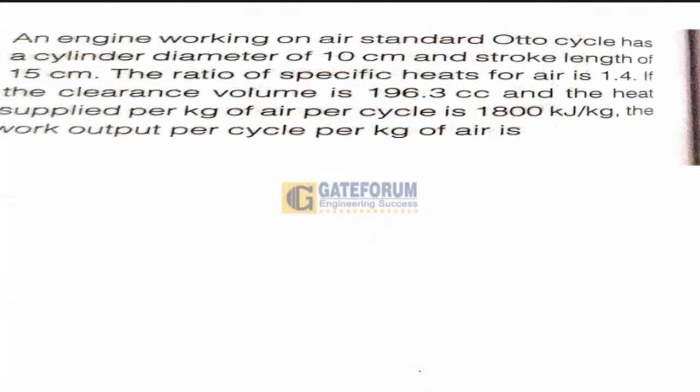Take this question. An engine working on air standard Otto cycle has a cylinder diameter of 10 cm and a stroke length of 15 centimeter. The ratio of specific heats for air is 1.4. If the clearance volume is 196.33 cubic centimeter, and the heat supplied per kg of air per cycle is 1800 kilojoule per kg, the work output per cycle per kg of air is?